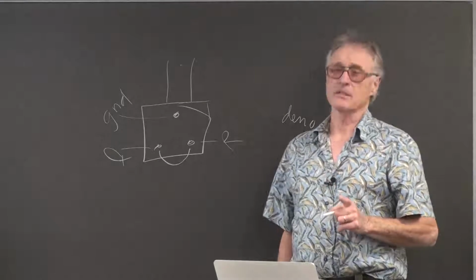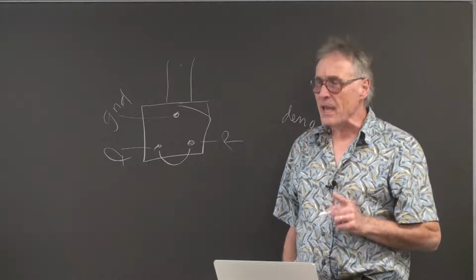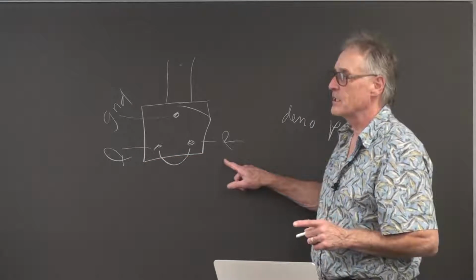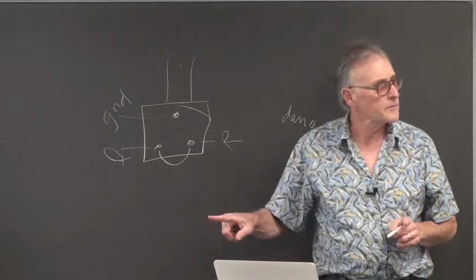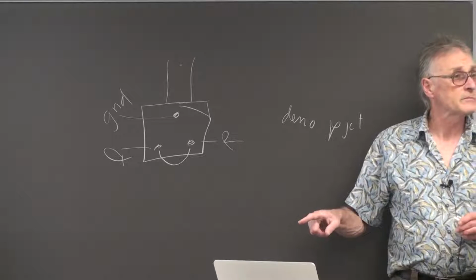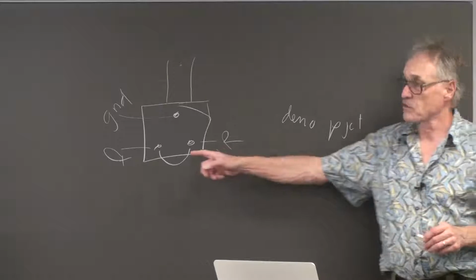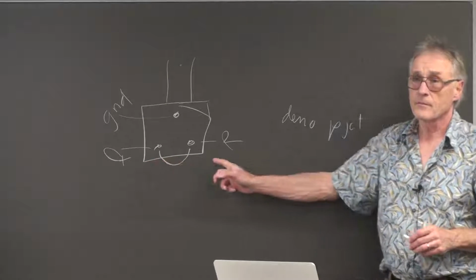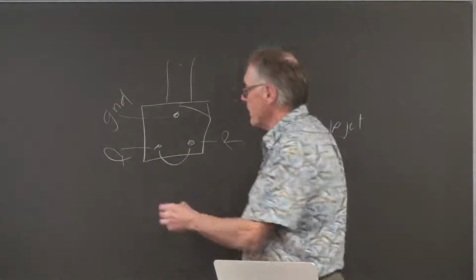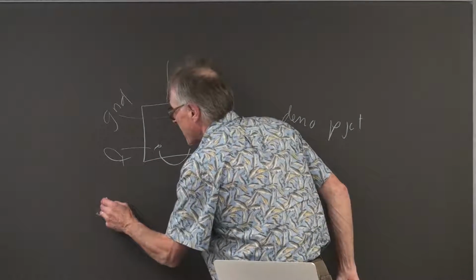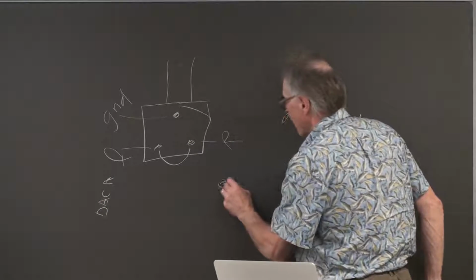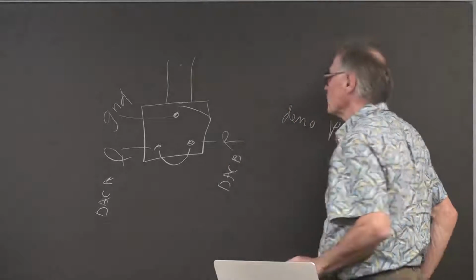What happens then depends on the impedance characteristics of the left and right channel outputs. It might just destroy both channels of the DAC because you're hooking 2 voltage sources together. Remember that you're going to have DAC A hooked here and DAC B hooked here.